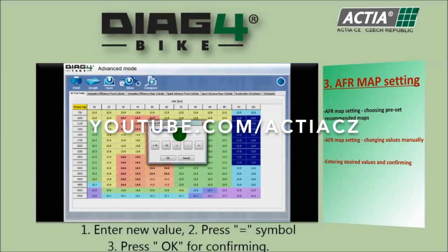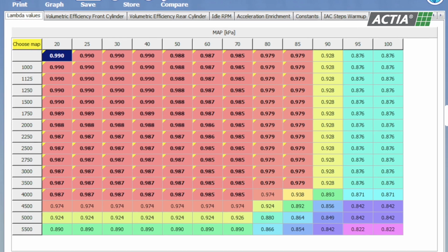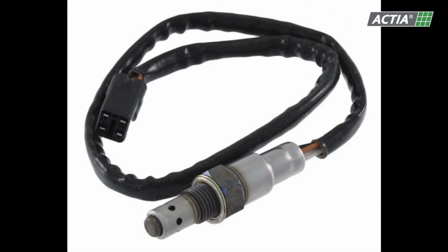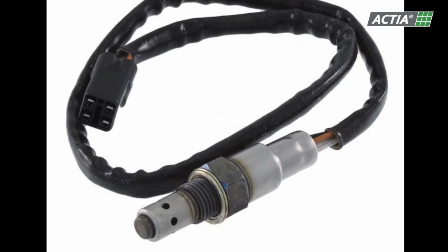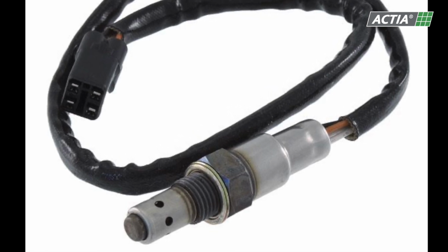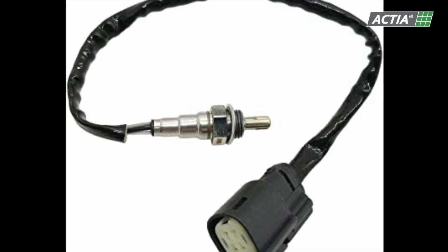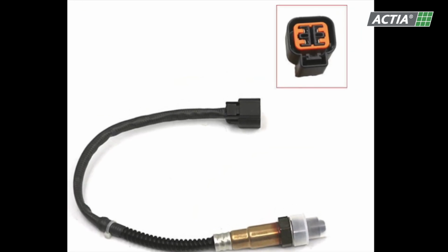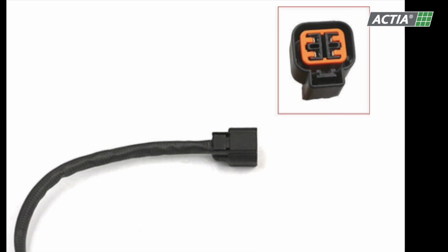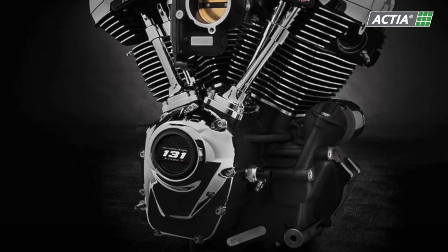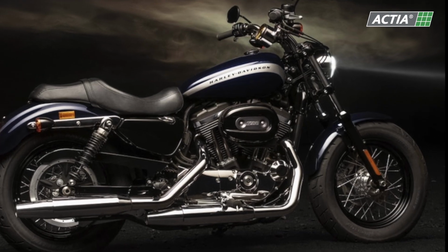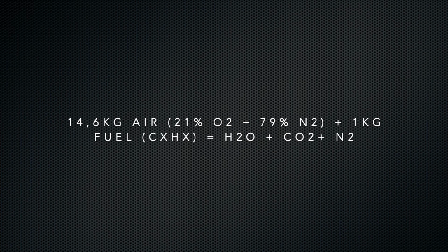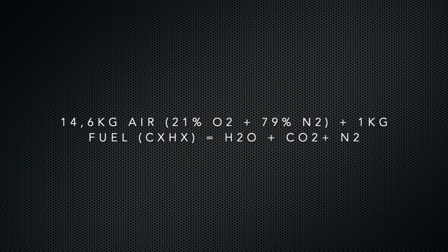Fuel maps describe how much air a given engine construction is able to supply to the combustion chamber of the cylinder and how much fuel needs to be added. The result of the actual combustion process is then monitored and regulated to a limited extent by an oxygen sensor built into the exhaust. The oxygen sensor thus corrects the real air-fuel ratio of the combustion process in relation to the type of fuel used, changes in the motorcycle caused by production tolerances, wear on individual engine components, and its accessories, etc. The goal is for the engine to operate in defined map areas at the stoichiometric ratio. It is a ratio where fuel is used most optimally. These specific fuel map areas should primarily cover modes the engine runs in while in city traffic.